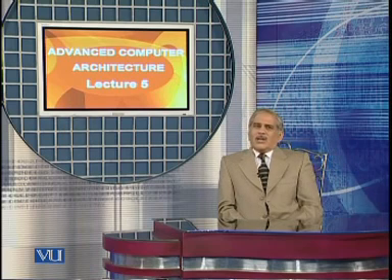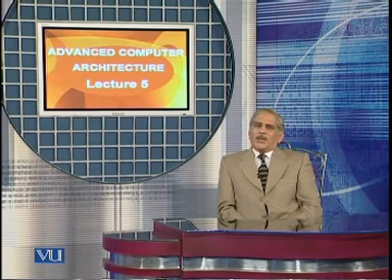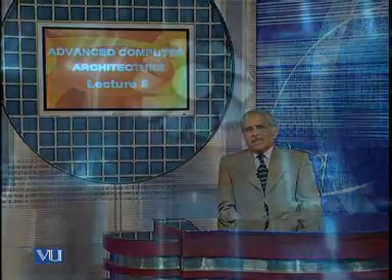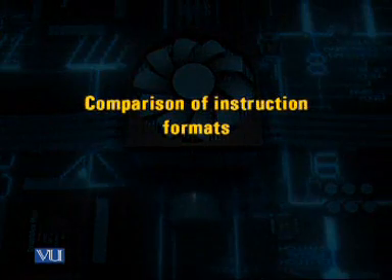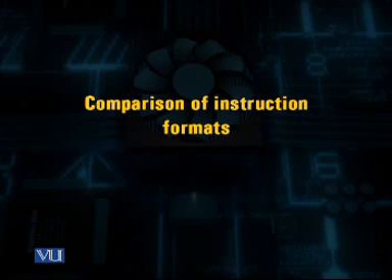So for this purpose, let us consider a case where we assume that the instruction opcode is of 1 byte, the address of the memory can be written as a 24-bit long address, and the size of the data bus is 8 bits. Let us consider this slide and see how we can find out the total size of the instruction word.